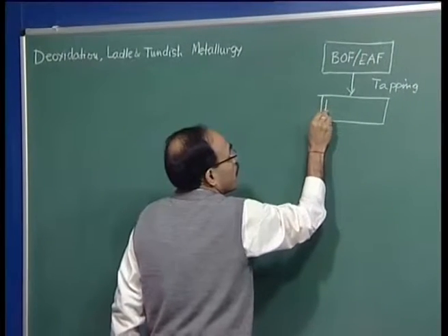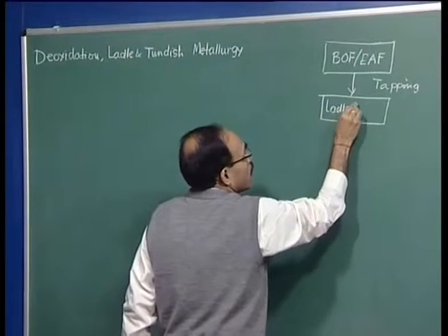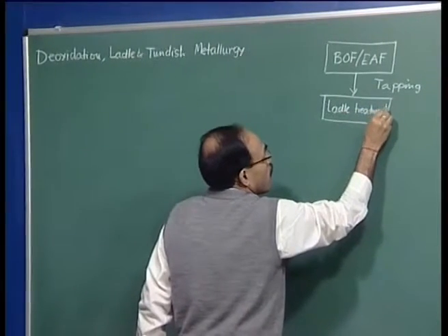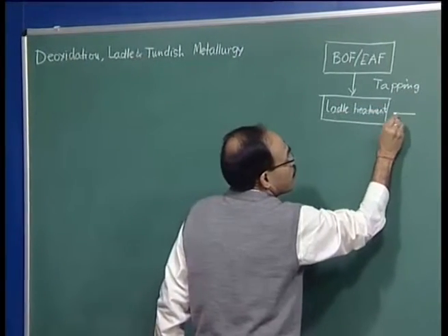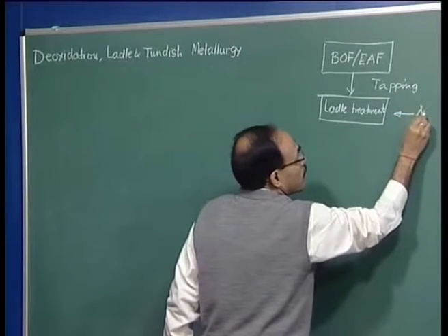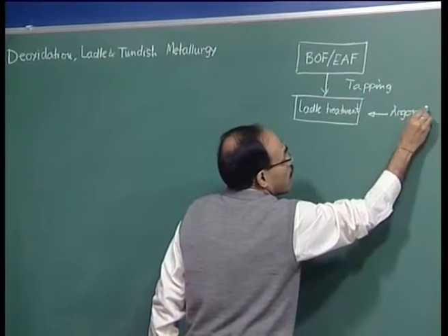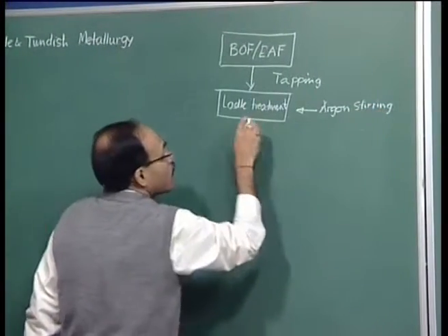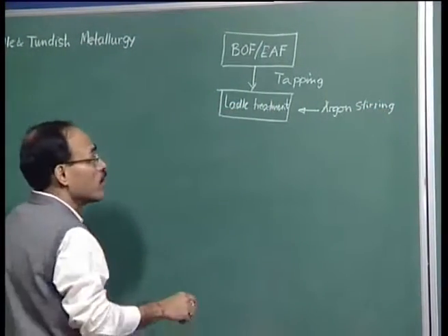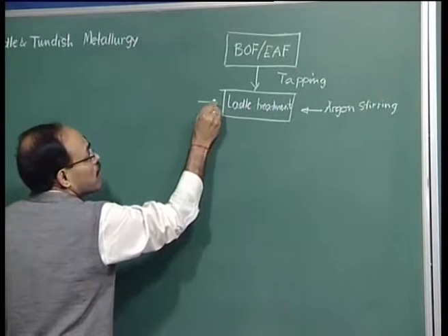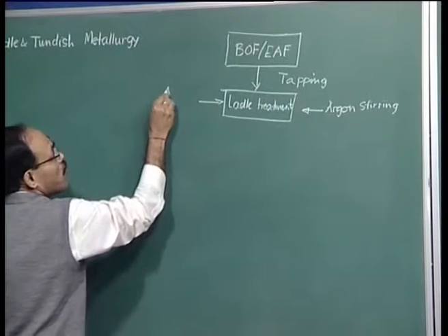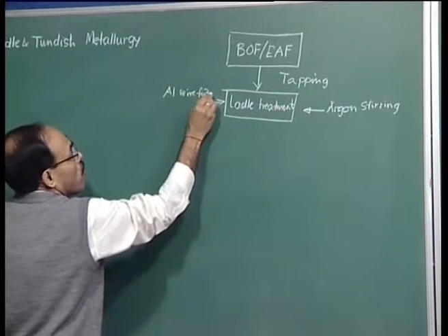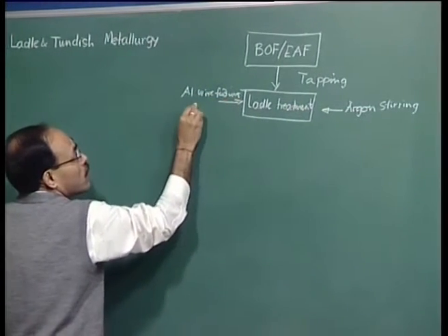And we have ladle treatment, and basically in this ladle treatment we are talking about argon stirring. What we are doing in this ladle following tapping is nothing but deoxidation. Maybe we are doing aluminum wire feeding or bulk deoxidation.